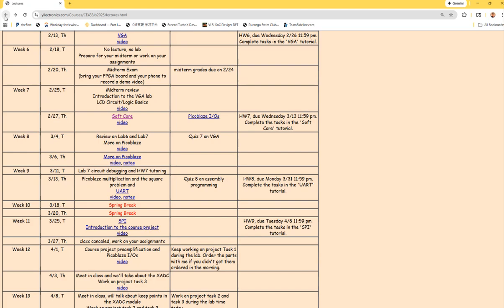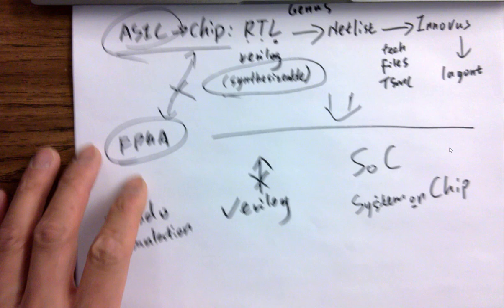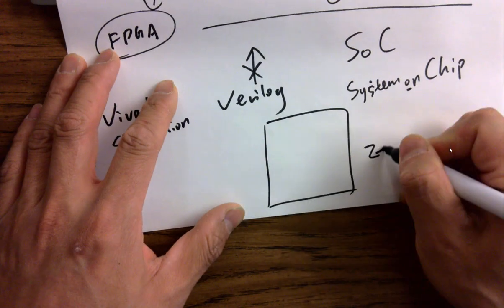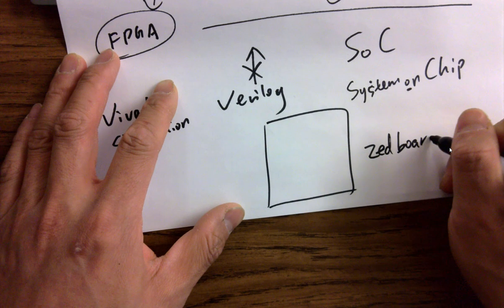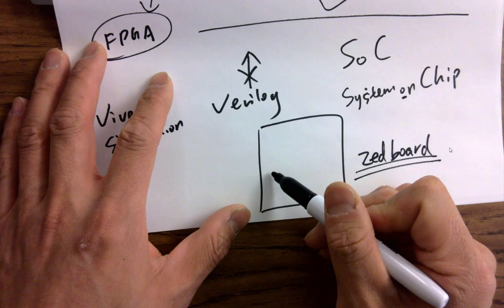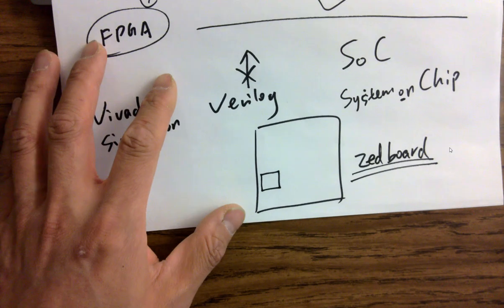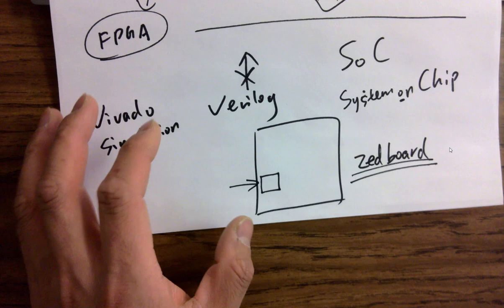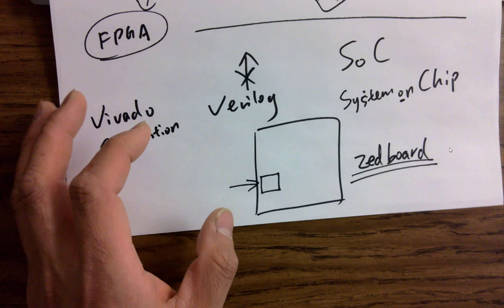A hard core is a CPU that the digital designers, for example, here's a Zboard. I showed you last week. That's a more expensive one, the Zboard. It has an ARM core over there. That ARM core is already designed and fabricated into the FPGA, and you are not able to change it. So it's a hard core.